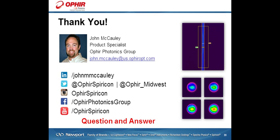Let's just take laser power for instance. If you have a laser power that is X and it is still X at the end of 2 minutes, then I'm going to say you've got a good laser source. I wouldn't change anything. I wouldn't worry about anything. But if you turn the laser on, it comes up to X, and then you start to see that graph or that number decrease, something is wrong with your laser.